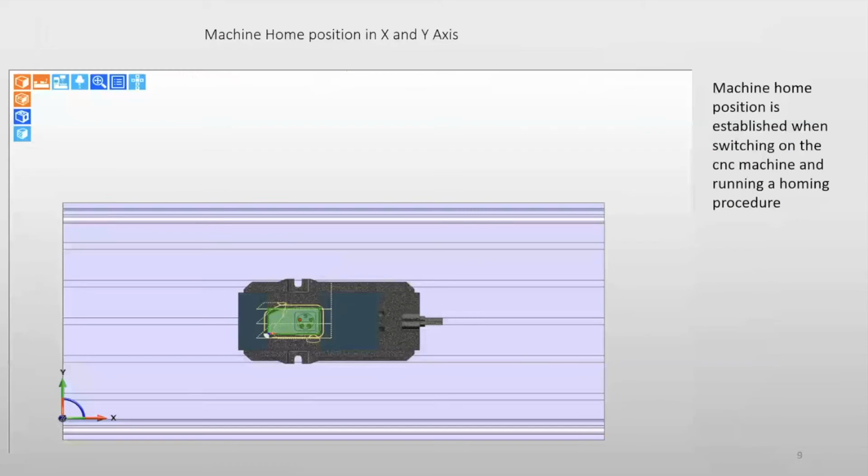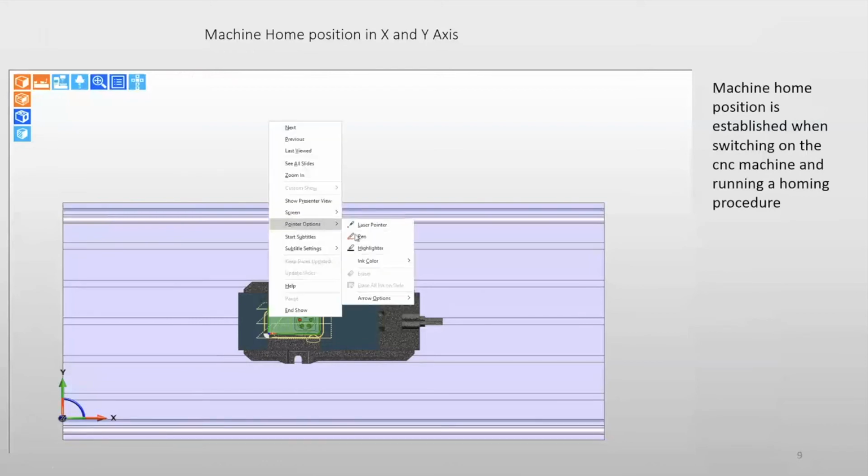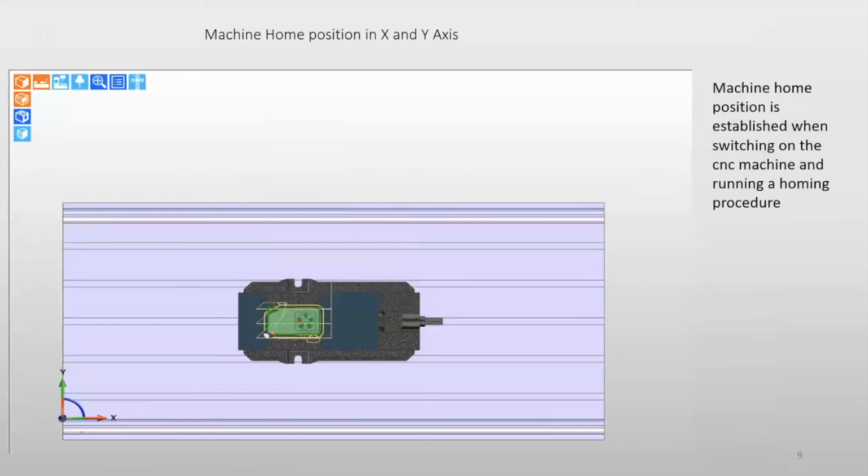If you remember, this is a presentation I used to deliver for level 4s. That gives you a better idea. Here you can see the machine coordinate system, and that's the workpiece coordinate system. If I don't zero the machine, and I tell the machine to go 10 millimeters in positive X, it goes from here. It doesn't do any cutting.